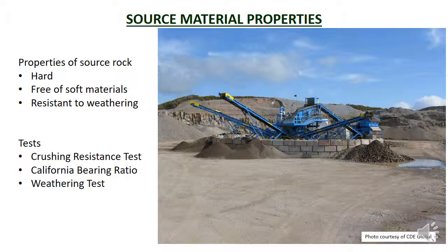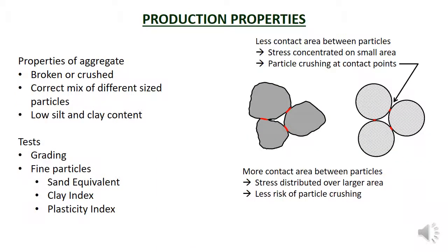This section also sets out the amount of testing required. If the rock being quarried changes, then a new test needs to be done, or a new series of tests need to be done. However, if there is no change in the rock, then tests still need to be done, only one sample for every 10,000 cubic metres of rock quarried.